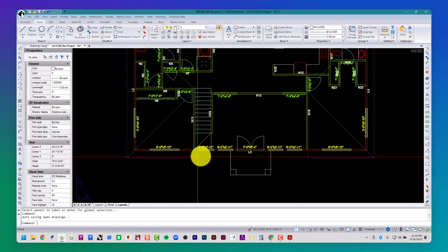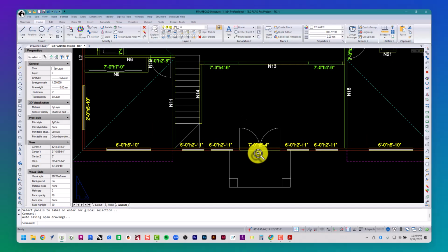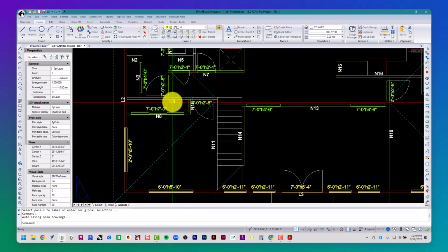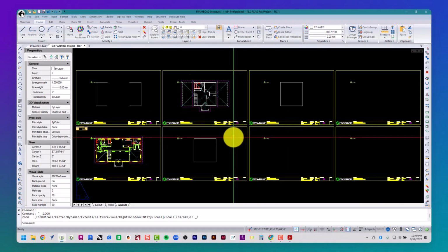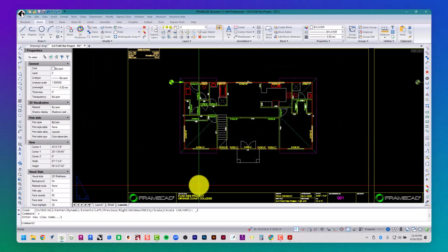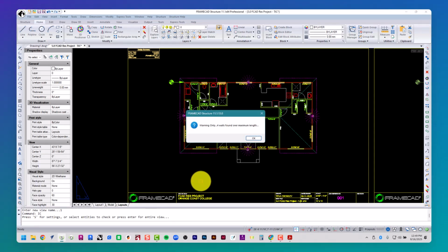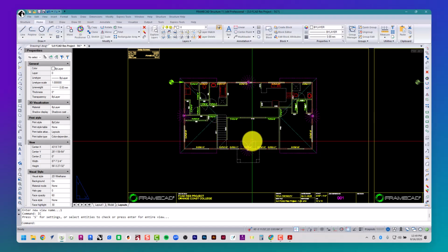So now, with that in mind, I can run the integrity check again. I'm going to quick navigate right back to border number 1, IC for integrity check, enter. And now I'm not getting that warning that I have 27 walls that are not labeled. Okay, the only thing that I have is 4 walls over the maximum length. So that's great. I'm going to go ahead and file. I want you guys to save it. I'm going to go ahead and save it as 6.0 just to prep myself for the next recording and lecture. So I'm going to hit save. Okay.